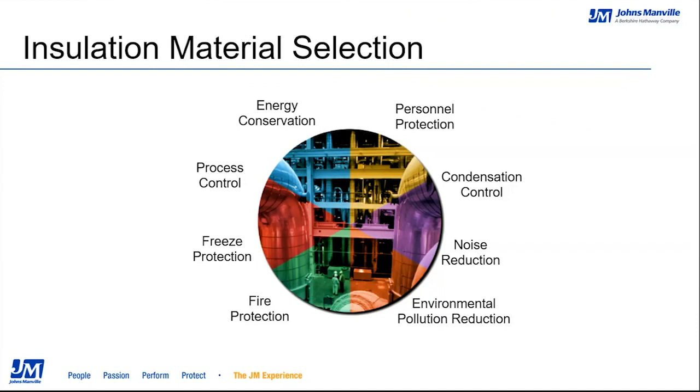That's a really important feature of insulation as well. And the third thing on here that I'd point out is condensation control, making sure that you're delivering the air coming off of your air handler to the occupied space and you're not creating any condensation issues for the insulation or for the system itself. So lots of really good reasons why you need to insulate.